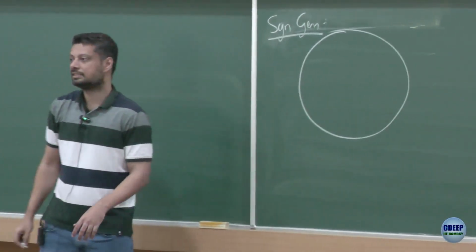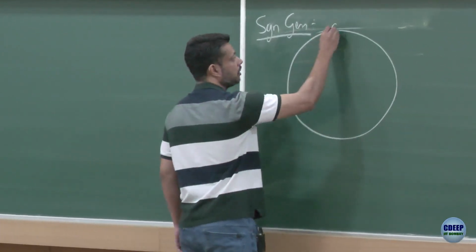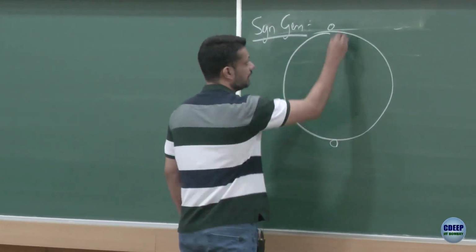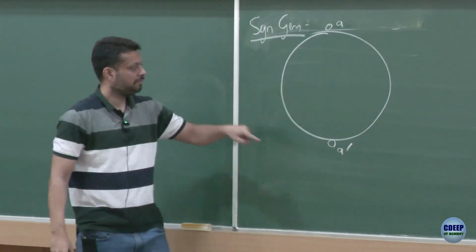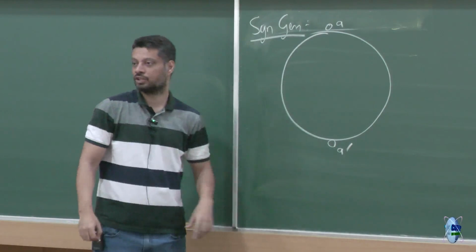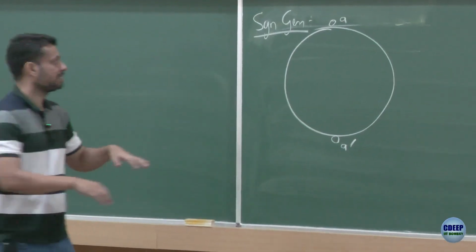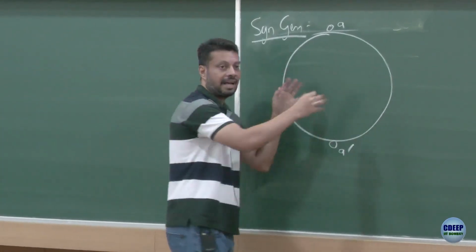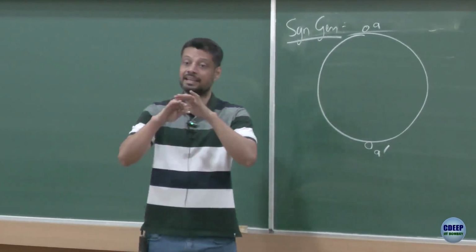This is the stator of a synchronous generator, right? These are your A phase winding. Let's say this is A, this is A prime, right? So your A phase winding is, let's say, wound like this on the stator, right? And your rotor is somewhere inside, and the rotor has either permanent magnets or electromagnets, which is creating an air gap